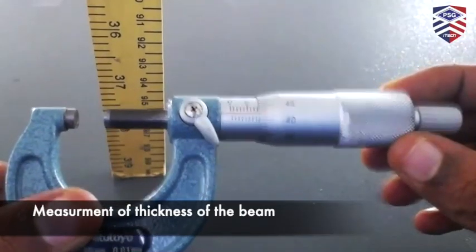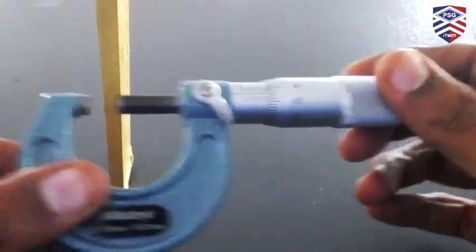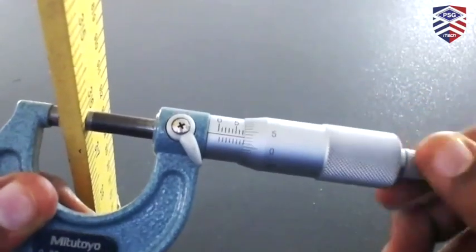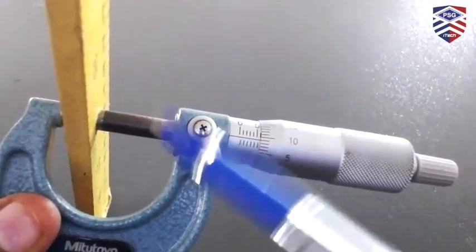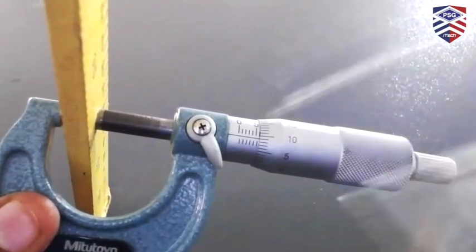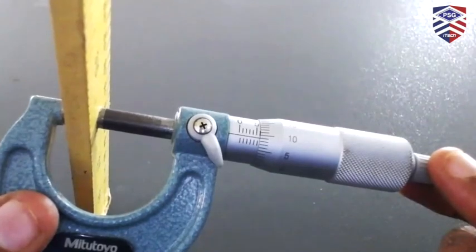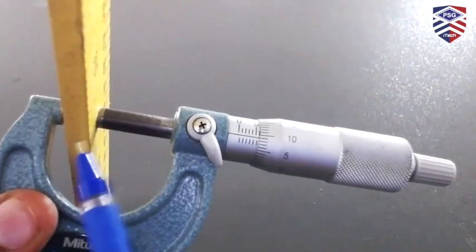Now let us see how to determine the thickness of the given beam. Rotate this until the scale is being held by the screw gauge clearly. So now we'll ensure the spindle and the anvil hold the scale, and to ensure its stability, we'll rotate the ratchet, and if it gives one small indication with the sound, we confirm the spindle has held the scale clearly.